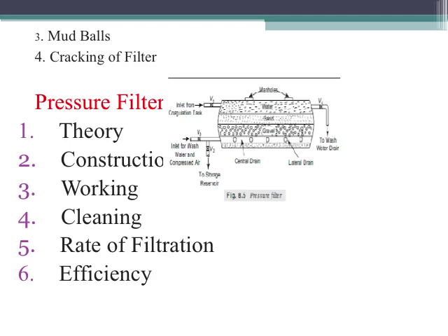The rate of filtration that can be obtained from rapid gravity filters is very high and is generally of the order of 3000 to 6000 liters per hour per square meter of the surface area. This high rate of filtration leads to considerable saving of space and even of filter materials.